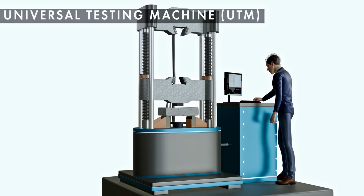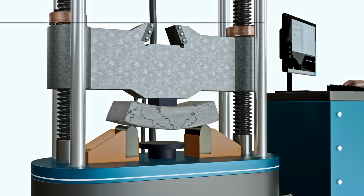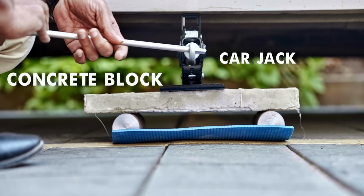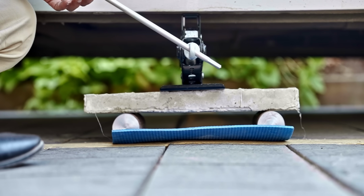Generally, engineers use a universal testing machine to test the strength of concrete. But I'm going to teach a crude method to compare strengths of different concrete without using a UTM, a method using your car. This is my simple arrangement. Just raise the jack, and you will be able to transfer a good amount of the car's weight to the concrete block.